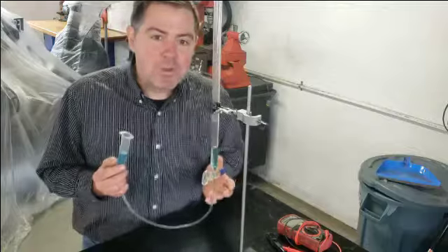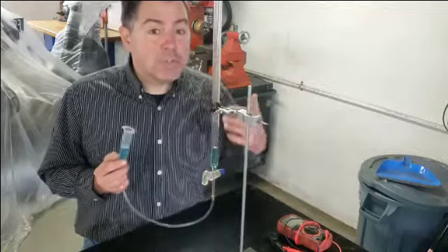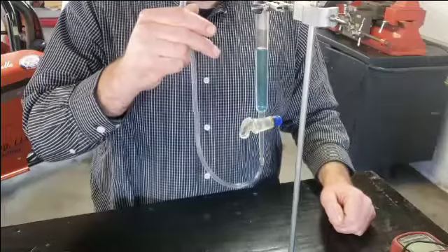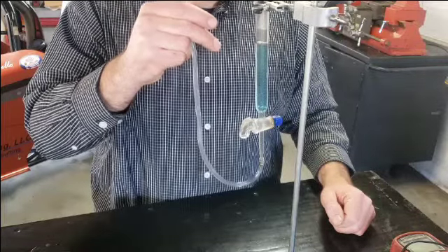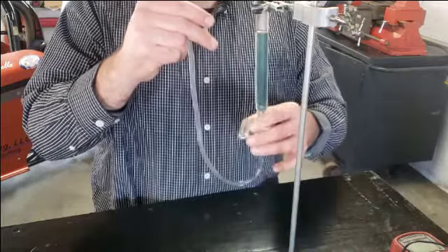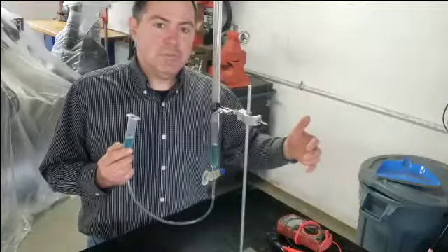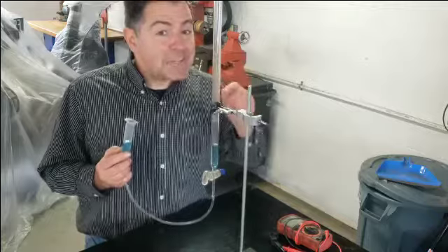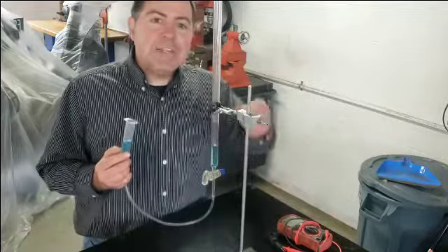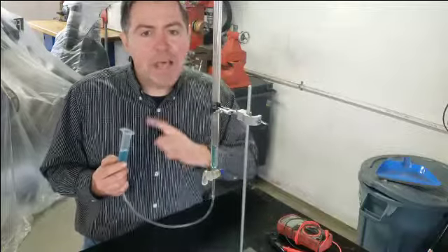Conversely, we know that as that fan motor is spinning, it's also creating an electrical potential, but in the opposite direction. We call that counter electromotive force. And that is actually a benefit to us at times, because what that does is it controls the current going to that fan motor.